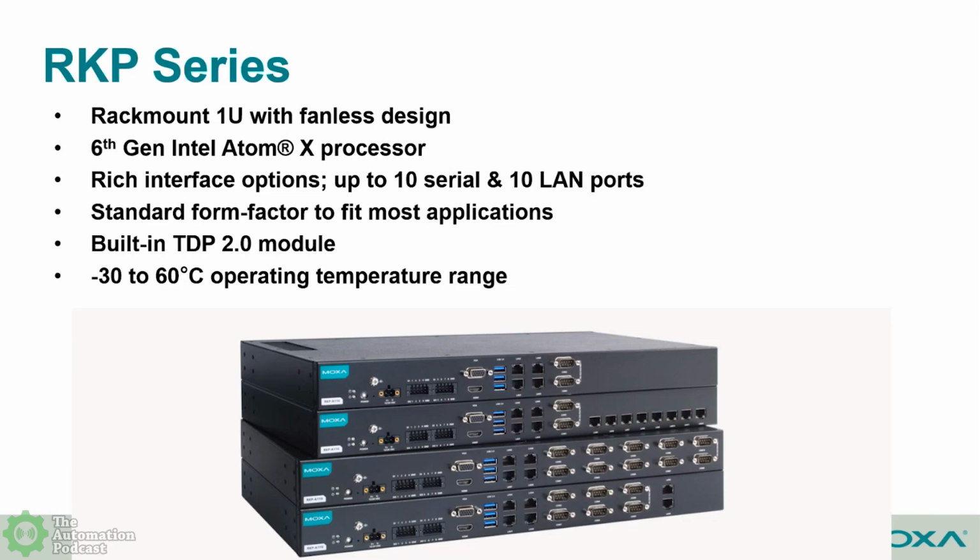It has SSD. It also has an external replaceable RTC battery design to deliver versatility. Also, like I mentioned, this is a rack mount, designed as a 1U fanless rack mount computer. And actually all the computers we have, the box, DIN rail, and the rack mount, are all fanless, because I think that's pretty much a requirement in an industrial PC. And it also has that built-in TPM 2.0 for security.